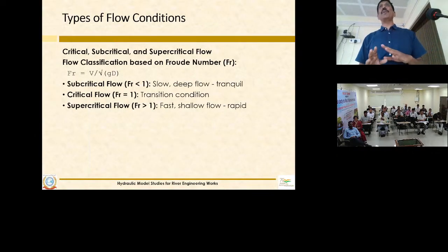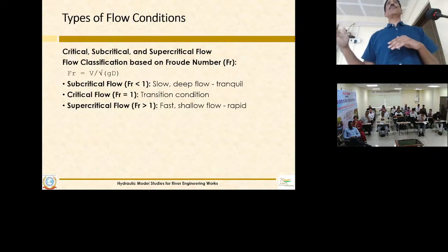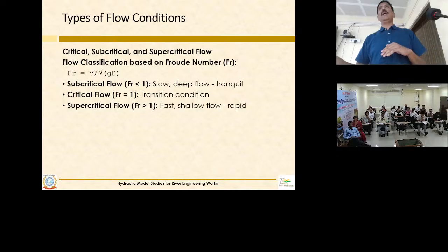The second type is the flow condition, and this is very important because, as Raghuram sir explained, there are various regimes and you must know in which regime you are modeling your flow. In the upstream region, the velocities are very high, and because of the high velocity the Froude number generally increases. When the Froude number is above the threshold, greater than 1, we say it is a supercritical flow. In supercritical flow, the boundary conditions are different from subcritical flow. In the supercritical regime, your boundary is controlled in the upstream region. That is very important to note.